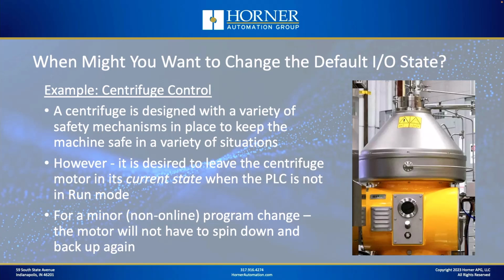Why would you do that? Well, that way, the motor doesn't have to spin all the way down and spin all the way back up again, just because you're doing a short download. Okay, so that's one scenario where you might change the default I/O state of a digital output.